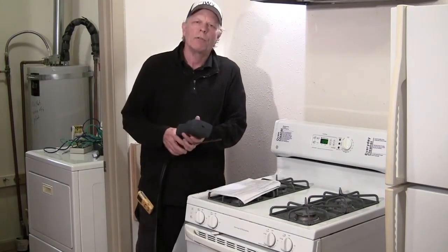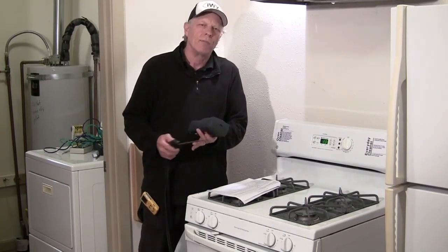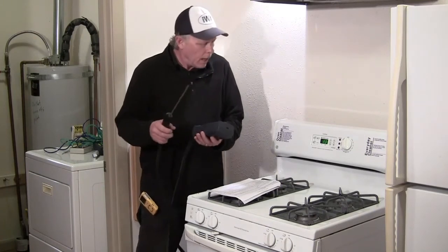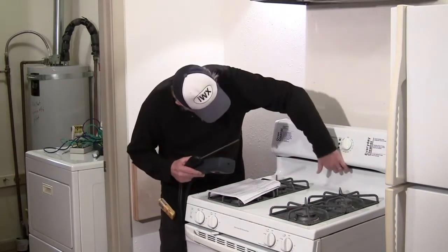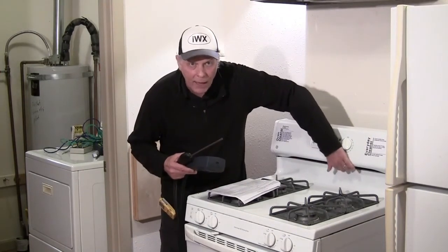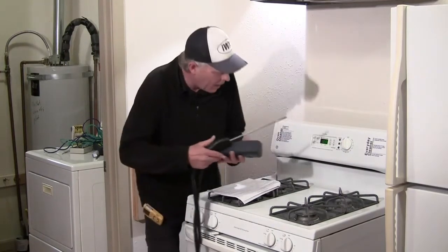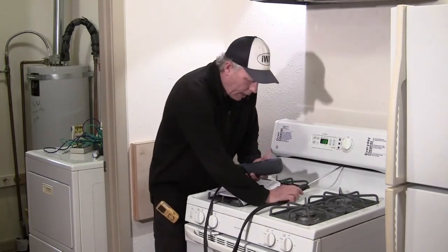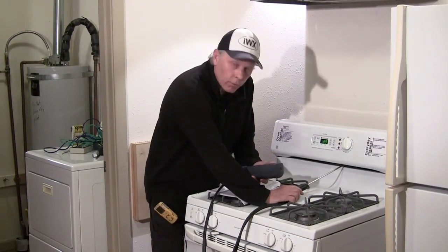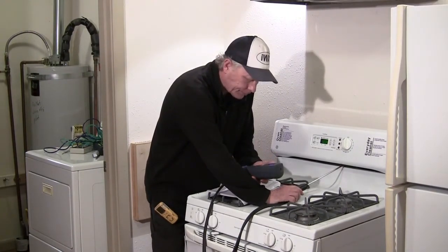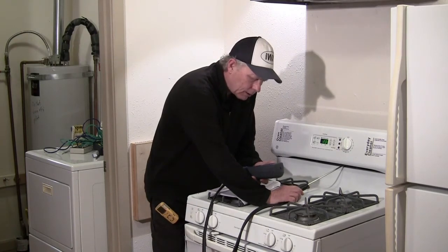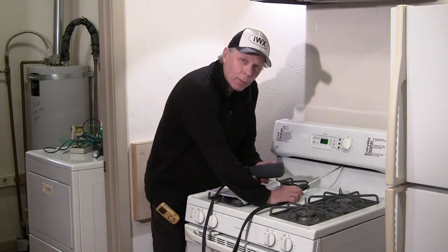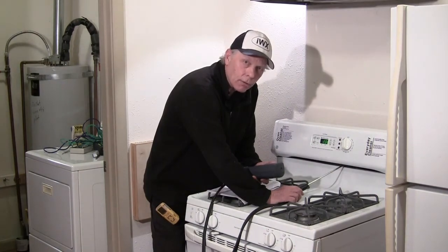We're on line 9 and it says candidate used appropriate sampling location for the oven test. I've had the oven running at 500 degrees for 5 minutes to reach steady state, and I'm going to take my as measured measurement at the proper sampling location, which is at the back here where I can feel the flue gases coming out, and we'll let it hold for a minute here, and it looks like it's jumping around a little bit. We have about 240 parts per million as measured CO.